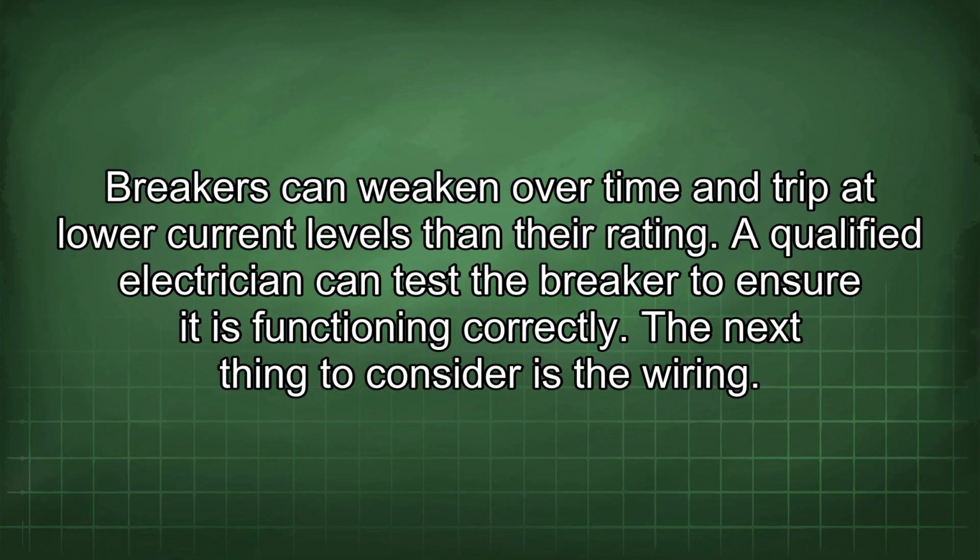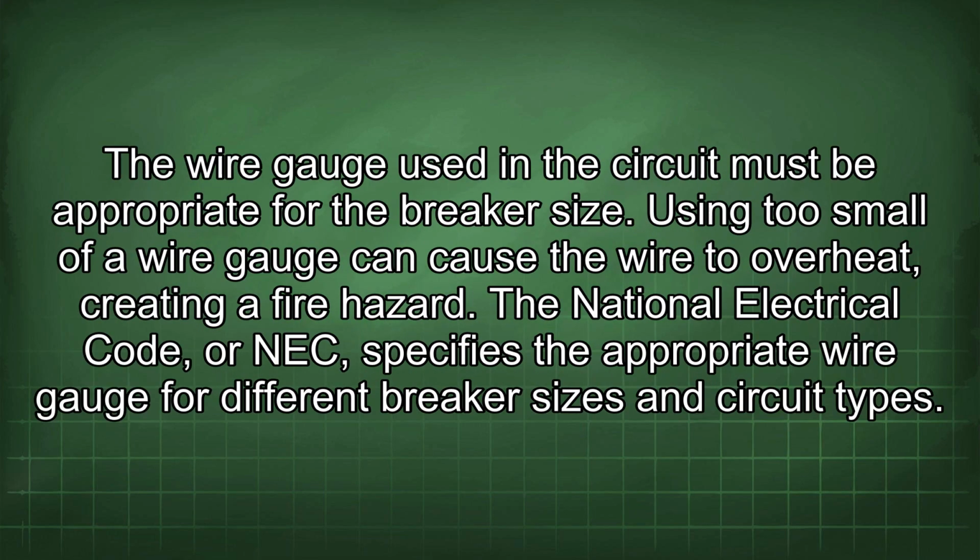A qualified electrician can test the breaker to ensure it is functioning correctly. The next thing to consider is the wiring. The wire gauge used in the circuit must be appropriate for the breaker size. Using too small of a wire gauge can cause the wire to overheat, creating a fire hazard. The National Electrical Code, or NEC, specifies the appropriate wire gauge for different breaker sizes and circuit types.